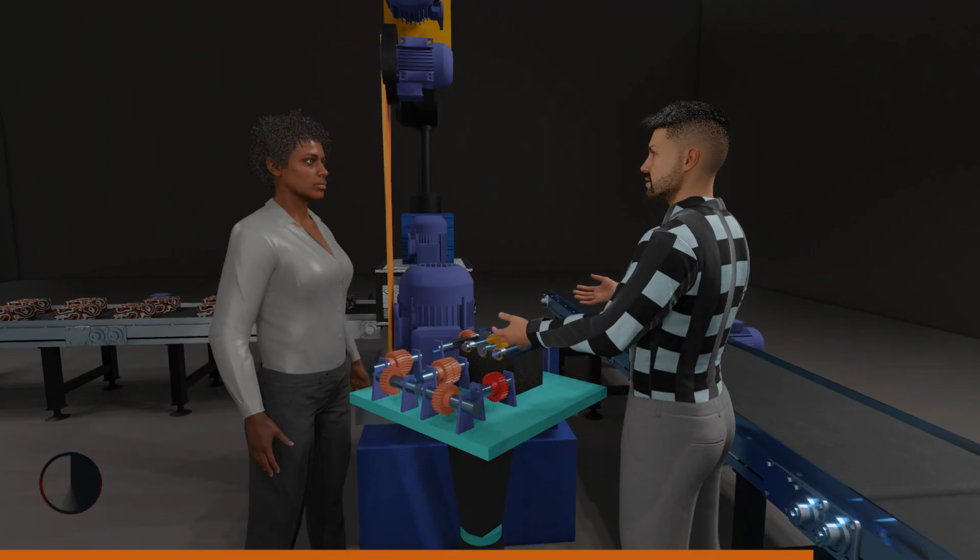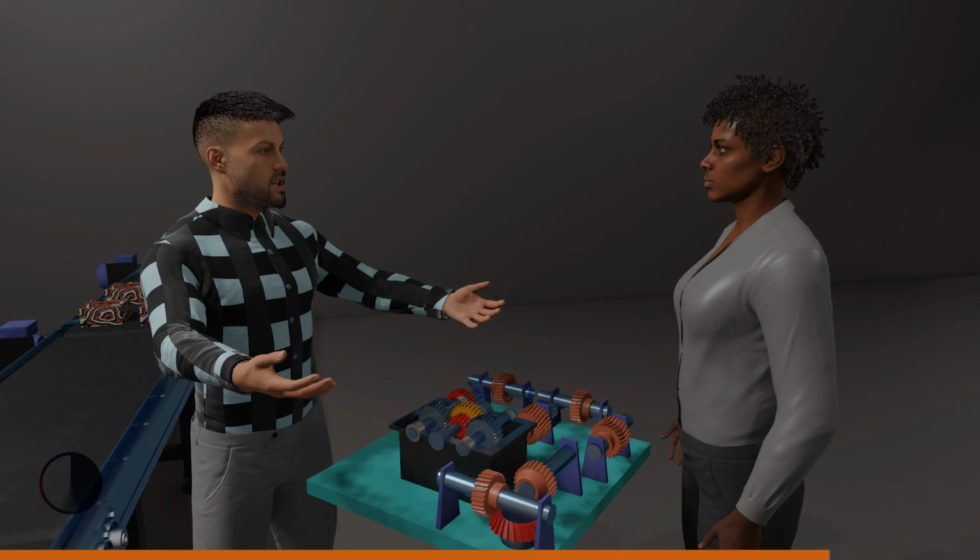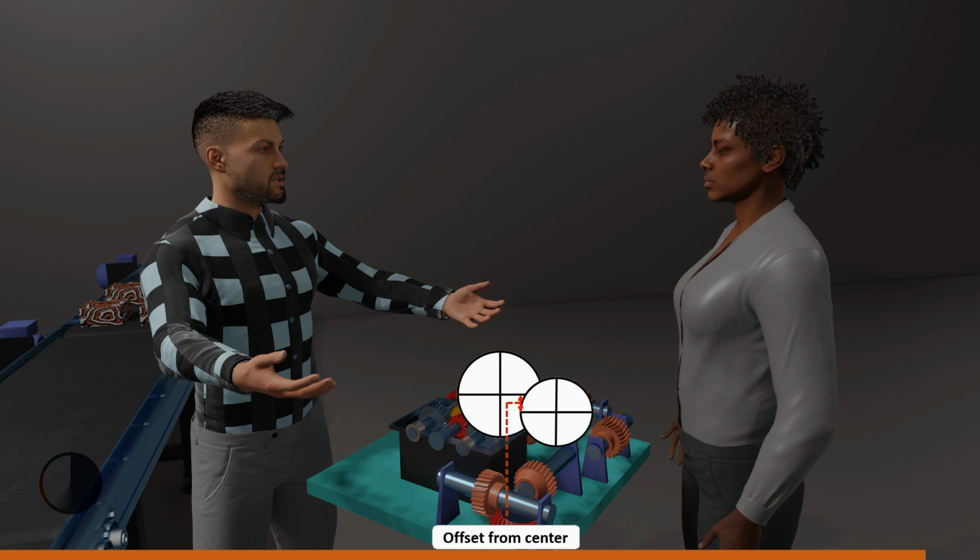In terms of design, it is similar to spiral bevel gears, just that hypoid gears come as cone-shaped gears, and the mating axes do not intersect during the gear set's arrangement. So basically, the gear shaft on the pinion side is usually offset from the larger shaft, which is the hypoid gear side.